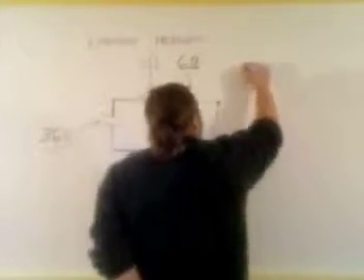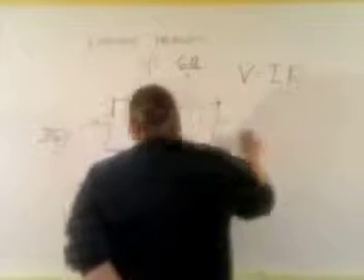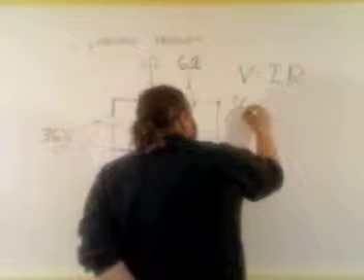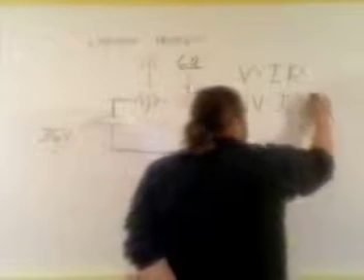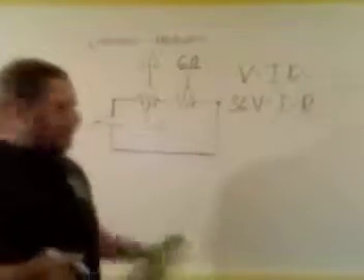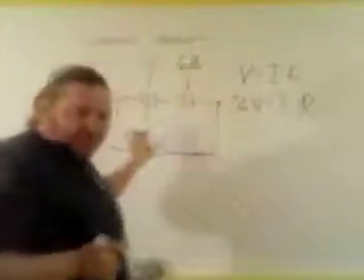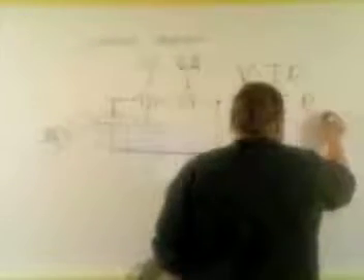So Ohm's law is V is equal to IR. Okay? The total voltage is 36. The total current is what we're looking for, and resistance. Now, we don't know the total resistance, which is what we really need to know to determine what the current is through the entire circuit. So I have to come up with a way of calculating the total resistance.